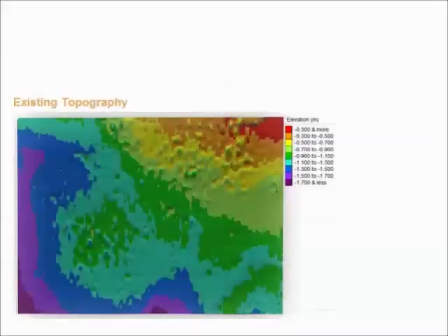So this field has naturally many small gilguys or craters, which are typically 30 metres or 90 foot wide and 0.3 of a metre or 1 foot deep. The gilguys severely limit surface drainage, which makes the field marginal for cropping. Ponding analysis shows 14% of the field experiences standing water. This creates waterlogging problems for crops in these areas, but also delays timely machinery operations for the rest of the field, waiting for the ponded areas to dry out.